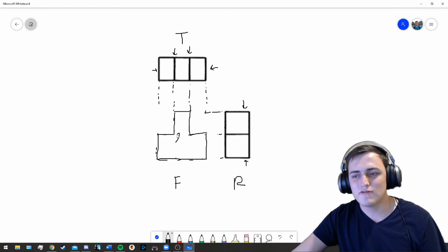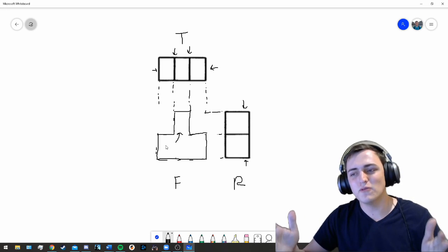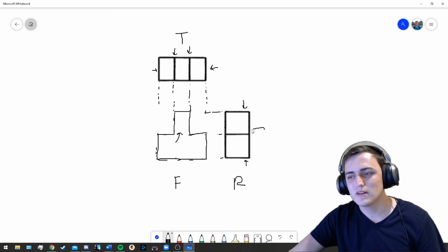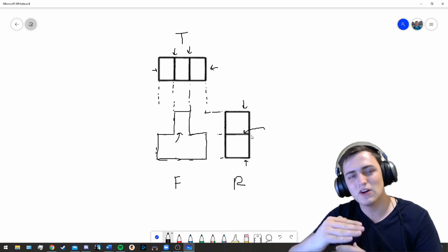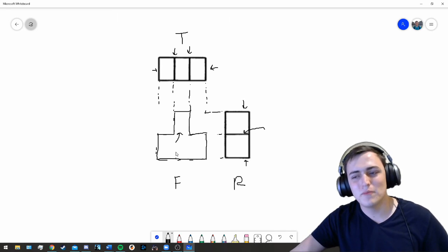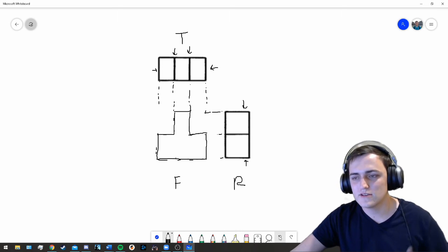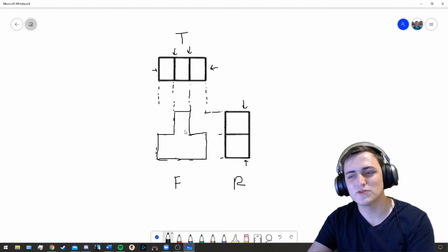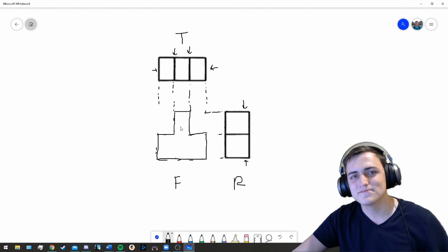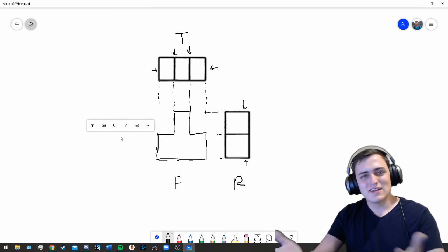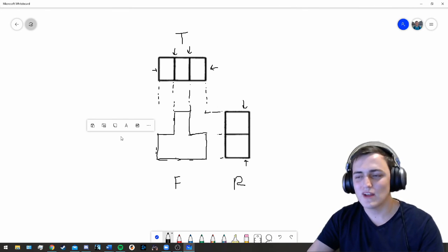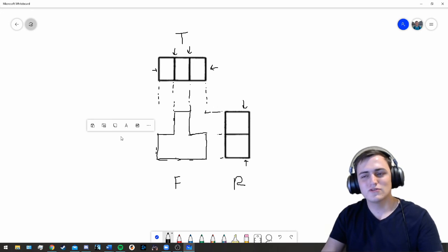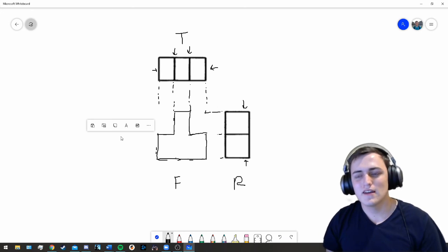And so we know we're going to have a feature that sticks up in the front view. And we know that in our right view, we have to fill the full width, and we know how tall it is from this line here. That line there tells us how tall this little bottom base feature is. And so from that information, we are able to conclude that the front view is just a simple upside down T shape. All right, that's going to conclude our interpolation of two isometric views to find the third isometric view.